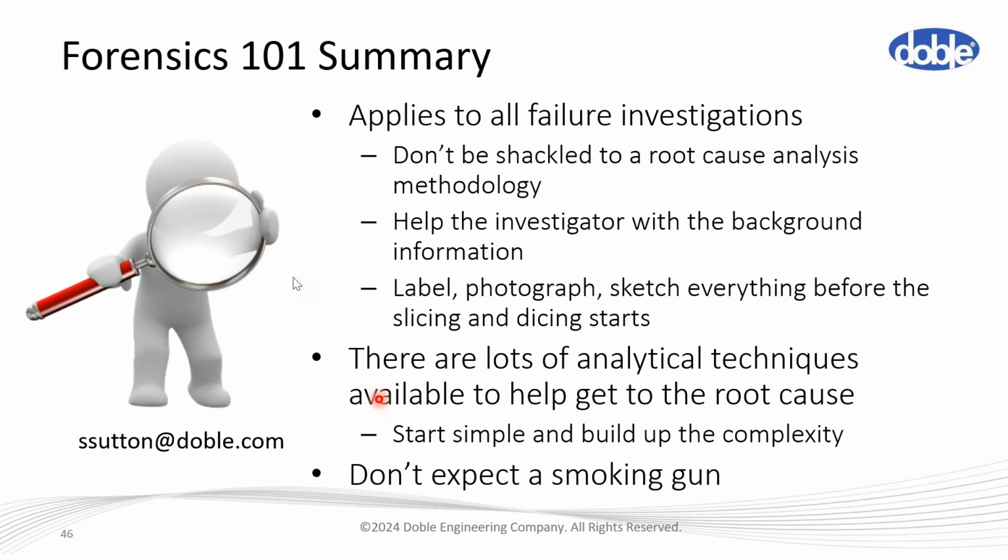Somebody's asked, did the splice installation instruction identify the required outside diameter of the connector? The answer to that is I don't know, because I never got any information on the type of joint. I could work out what the type of joint was. But normally the splice kits come with all the requisite parts. So I wonder whether in this particular case study I was talking about, the contractor tried to save money by buying all the various bits separately, and had caused the problem in that way.